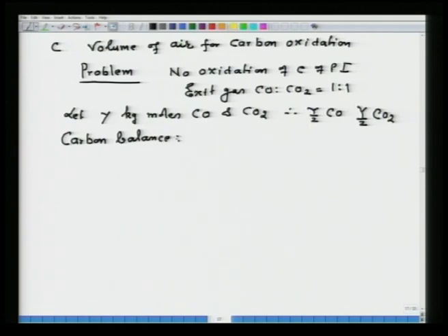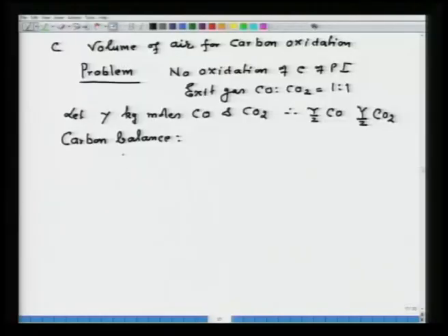From all sources, wherever carbon enters, the carbon of the coke, carbon of calcium carbonate, and it exits as carbon in cast iron and so on, you have to do this balance, and it results in this equation: 8.854 plus 0.26 is equal to y by 2 carbon in CO and y by 2 carbon in CO2. This is our equation number 1.